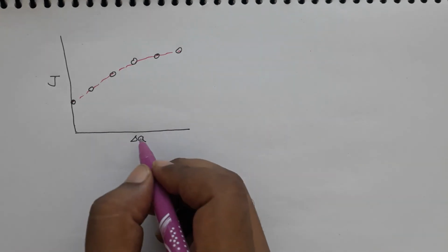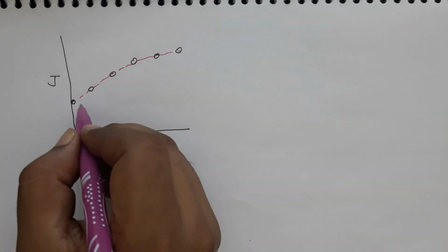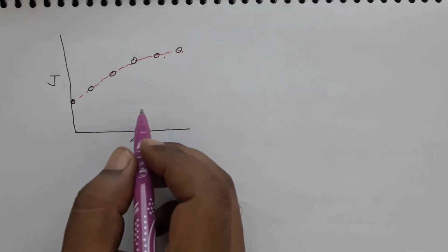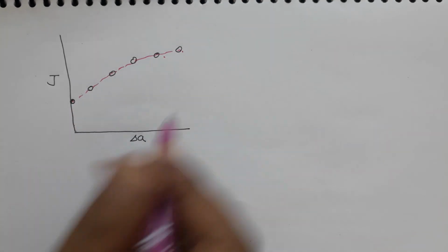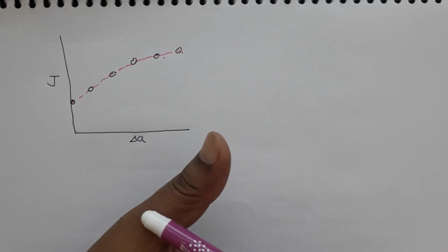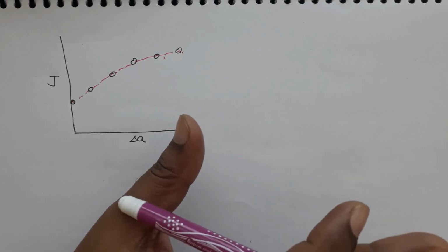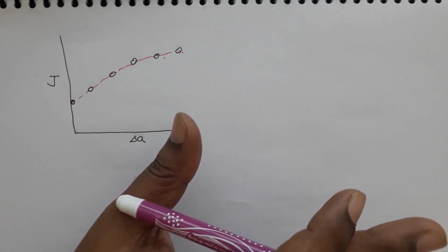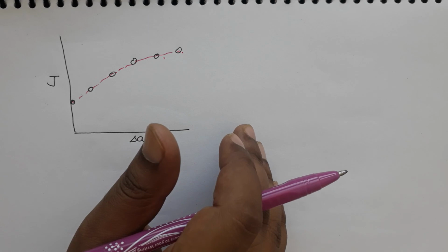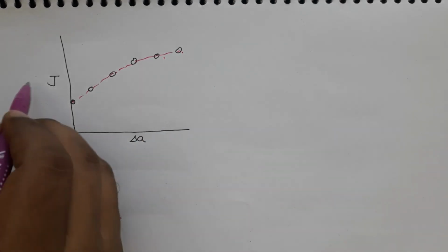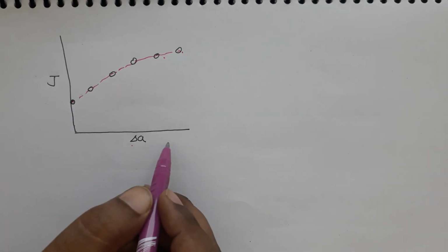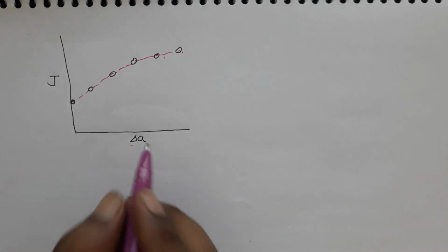Okay. So at different values of crack lengths, how many tests have you done? 1, 2, 3, 4, 5, 6. Then of course you have done 4 more, but that is not relevant. So that's how you get these points. These 6 points actually indicate 6 different tests performed for stationary cracks. Alright. So now the standard definition of how you get the fracture toughness of the material. So far what we are plotting is energy release rate as a function of crack length, okay, crack extension.